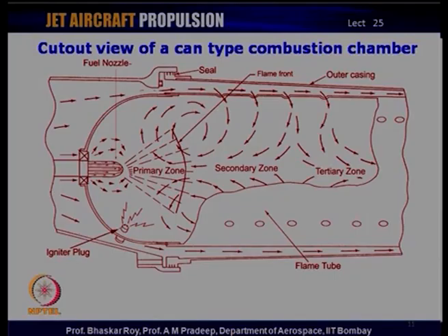This is pre-mixing before the combustion. We have two rounds of mixing, one before the combustion, one after the combustion. The first mixing is before the combustion. The fuel, evaporated from liquid to gas, needs to be mixed with air. So, you have a gaseous mixture of air and fuel before the combustion, and this needs to be uniform across the combustion cross section.